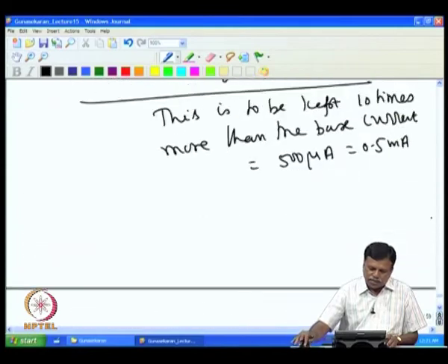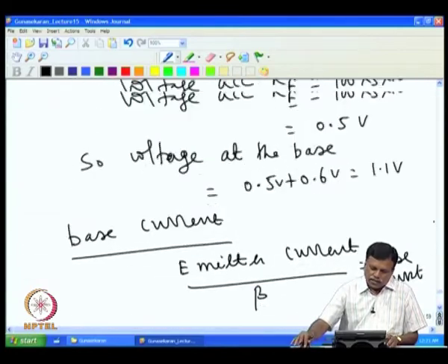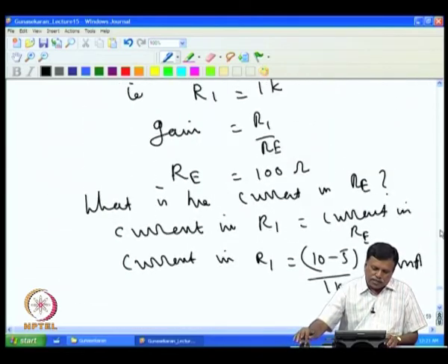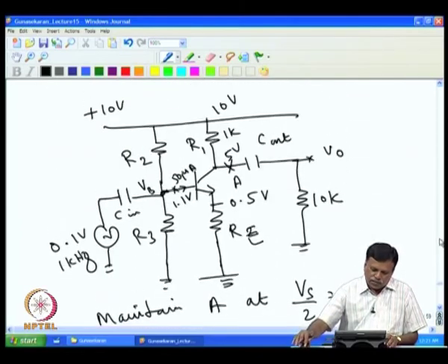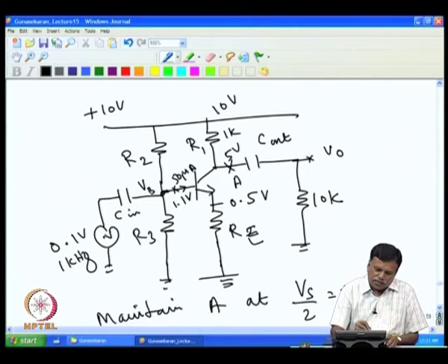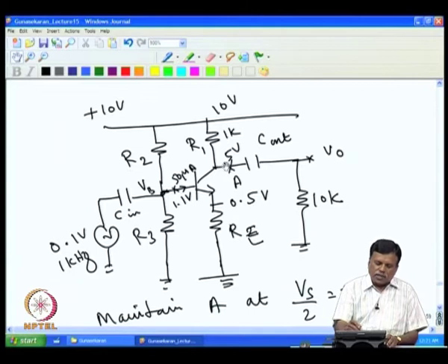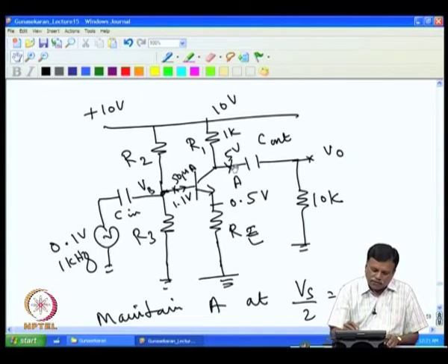collector, for example, in this case this amplifier works all right up to some point, beyond which it does not work. The limitation is that if I increase this voltage to say 1 volt, then I expect to get here 5 volt, 10 times amplified, that will be 10 volt amplified voltage supposed to come, and that cannot happen because the supply itself is 10 and what we have kept is only 5 volt as an operating point here. So, this works at 0.1 volt and it gives you here 0.5. If I give here 0.2, then I will get 1 volt.